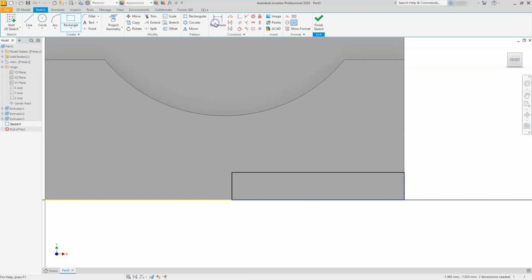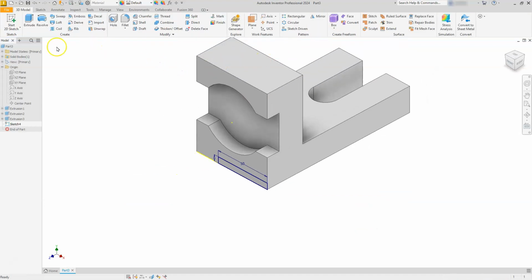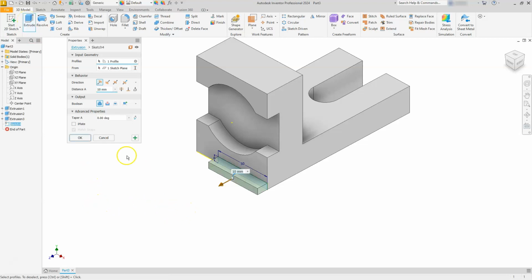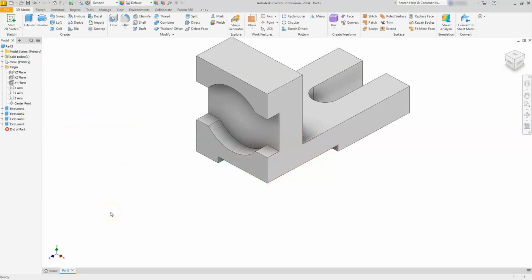Let's go ahead and put the dimensions on it, and we see that the distance here should be 50. The distance here is going to be 6. And that's all I need. You can see everything is fully constrained. Go ahead and finish sketch. Choose the extrude option. It's going to send it one direction, right? I want to make that distance 72. And then I'm going to reverse the direction to make it cut from here, and you're going to get the red showing you that it is subtracting. Go ahead and choose OK.